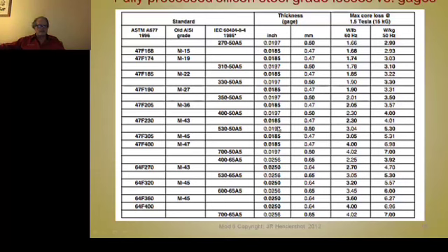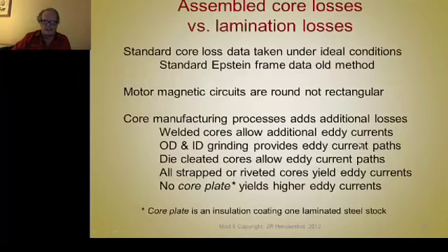But these are the charts that are used to measure core losses. The trouble is, these are given for one flux density and one frequency, or 2 frequencies. To calculate Steinmetz coefficients, you need more data than that. You have to have loss data for at least 3 different flux densities and frequencies, and that sort of data is becoming available. We're going to come back to the availability of that new core loss data in a minute.